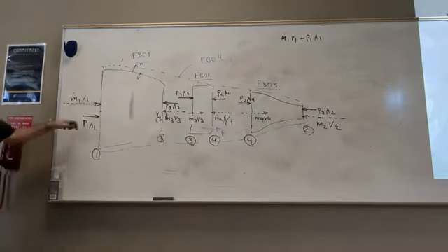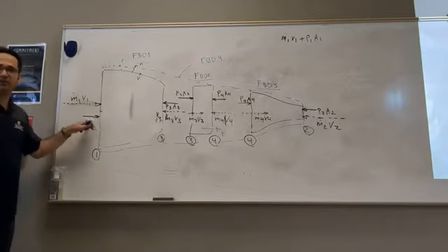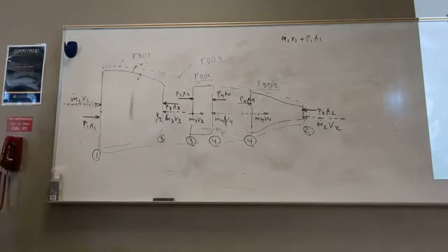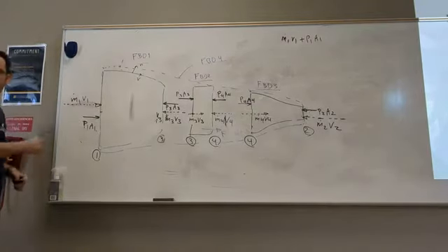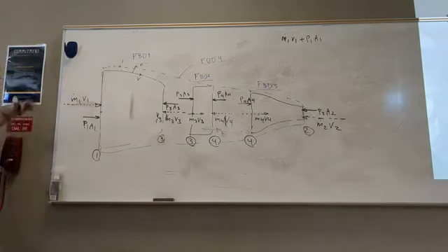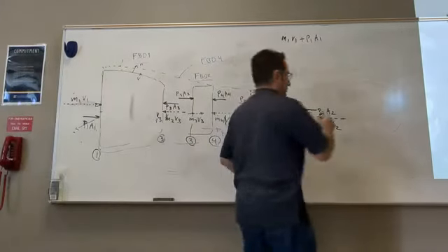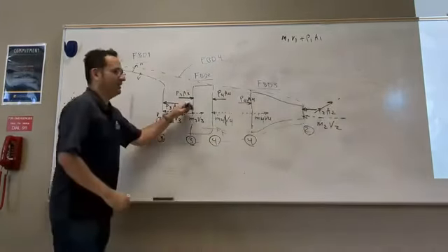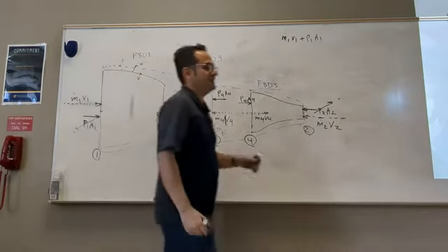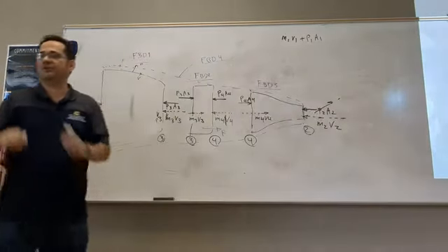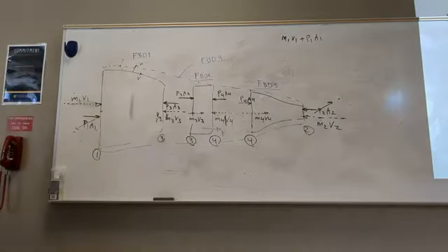So this is the pressure that I put on the FPD: it's P0 plus gauge, right? P0 cancels out everywhere, so it's just the gauge. What's the gauge pressure in the far field? This is far from the blade. What is P1? 0. What is P2? 0. What is P3? It's near the blade. Is that 0? No, there is some increased pressure. And P4 also has some increased pressure. But in the far field, it's just the atmospheric pressure.